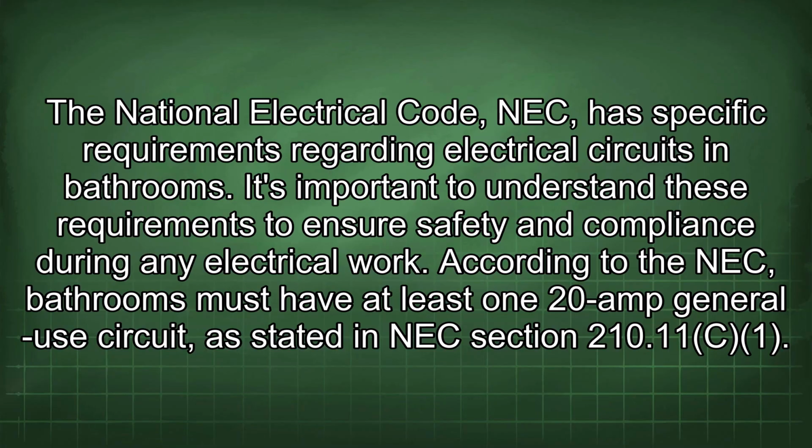The National Electrical Code (NEC) has specific requirements regarding electrical circuits in bathrooms. It's important to understand these requirements to ensure safety and compliance during any electrical work. According to the NEC, bathrooms must have at least one 20-amp general use circuit, as stated in NEC section 210.11